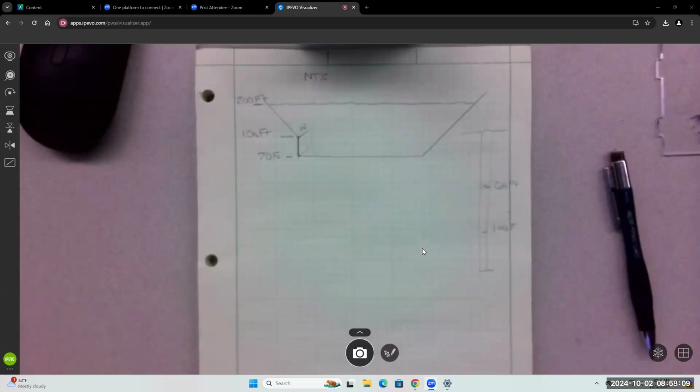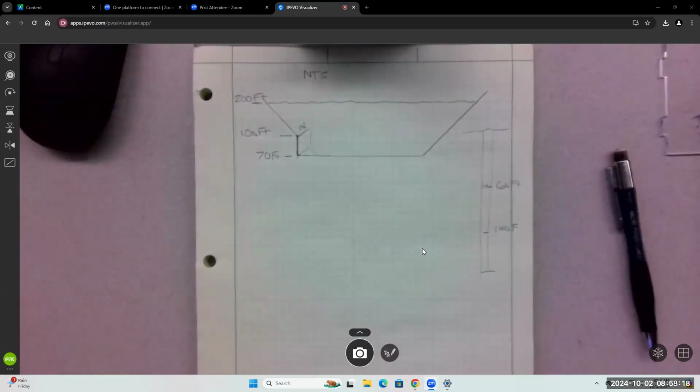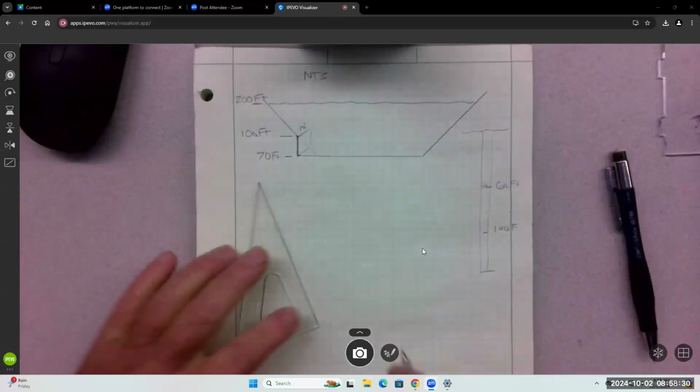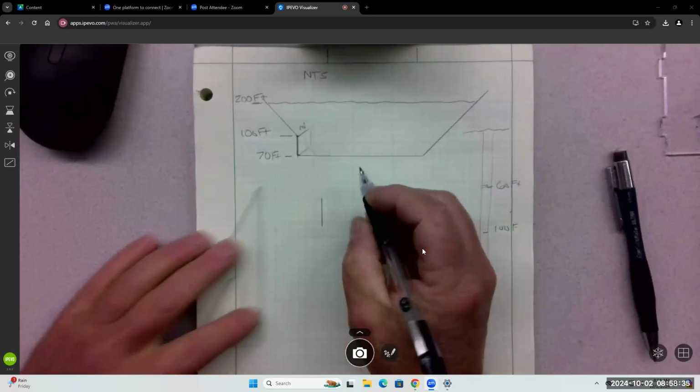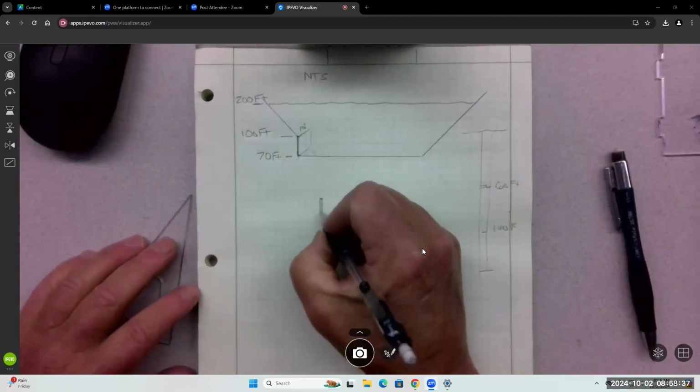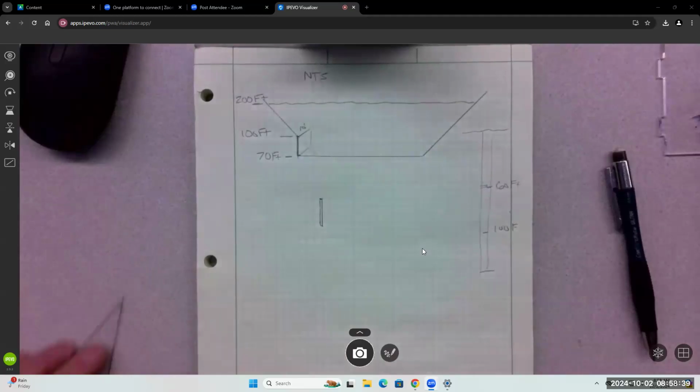Sometimes we'll want the distribution of the pressure, and we can do calculations with that too. Sometimes we want the hydrostatic force. So let's go for a hydrostatic force. We have to draw the diagram of the pressure curve to get that. If I was doing it, I'd pull the plate out and probably leave it two-dimensional, so it's some kind of plate, a side view of the plate.